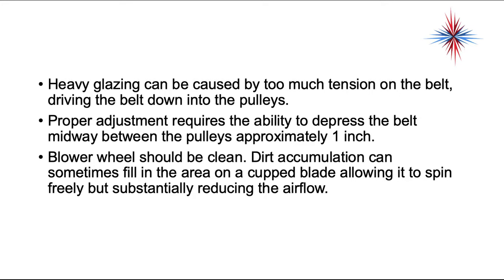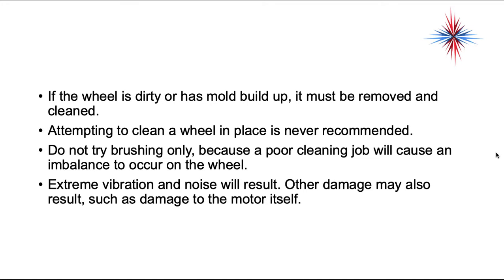The dirt accumulation on a blower wheel can sometimes fill the area on a cup blade, allowing it to spin freely, but it can really reduce the airflow. If the wheel is dirty or has mold buildup, it must be removed and cleaned. Attempting to clean a wheel in place is never recommended. Don't try brushing, because a poor cleaning job will cause imbalance in the wheel. Extreme vibration and noise will result. Other damage may result, such as damage to the motor itself.